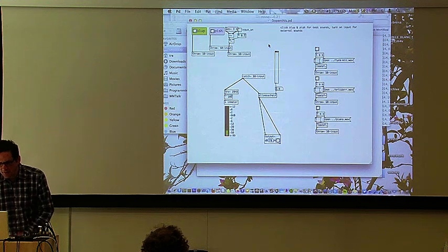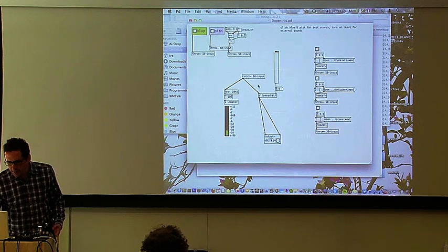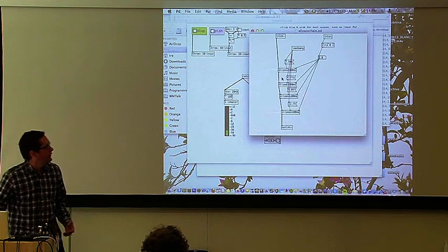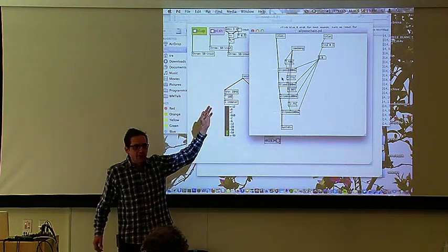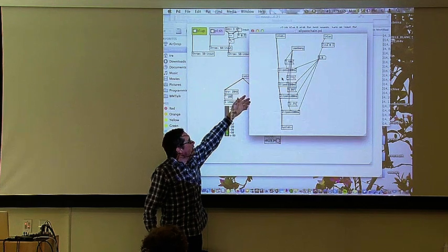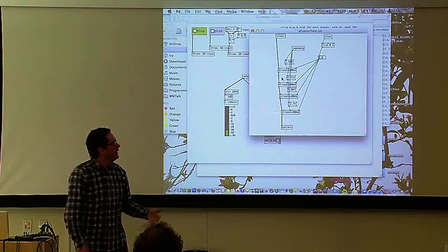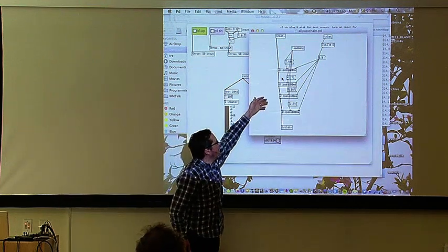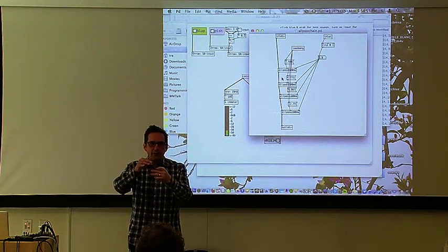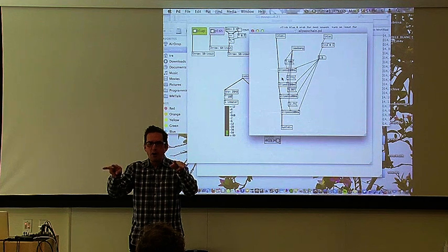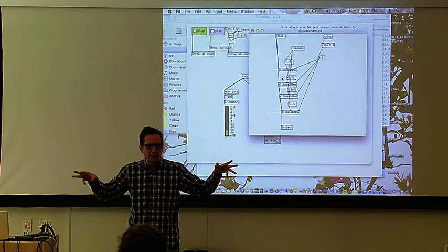Okay, I'll stop that. This is one of the keys to modern reverb, which Manfred Schroeder found out: using short time all-pass filters in the range of 1 to 15 milliseconds does a lot to fill in the echoes. And it's not just using one all-pass filter, but a chain of them, so that every echo from an all-pass filter branches off to more echoes that are now the compound of those times. So you get this quick diffusion.